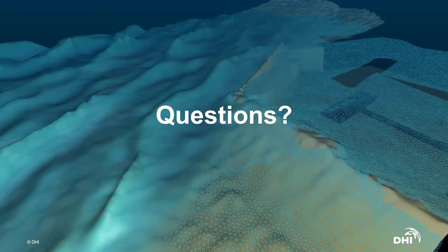Yes. You can also do that, Philip Van Loon, if you have your model and try and output a volume file using 0 time steps, then you would be able to output the porosity zones, or a porosity map, from the mesh that you have provided in the 3-dimensional Mike 3 Wave FM setup file.